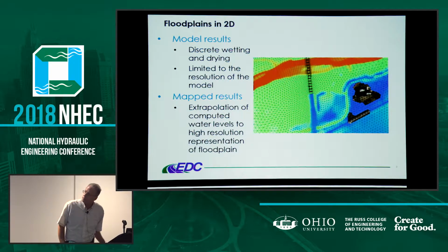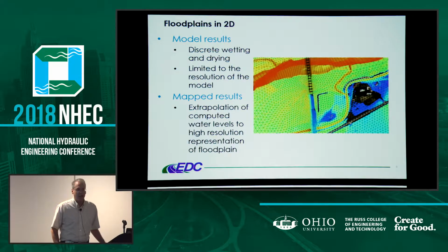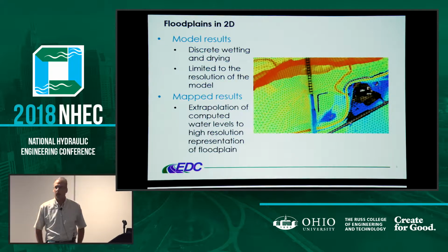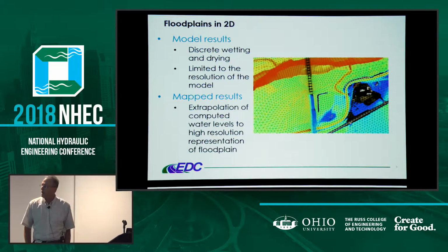And notice there's fairly consistent depths. The green colors show shallow depths, blue even more shallow, just barely wet, and the red is the channel. If we map that back to the original resolution, the high-resolution LiDAR raster data, you now start seeing individual channel cells, braided streams, and other depths. And by mapping that, we also aren't limited to the resolution of the mesh.